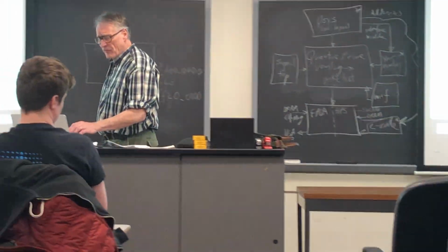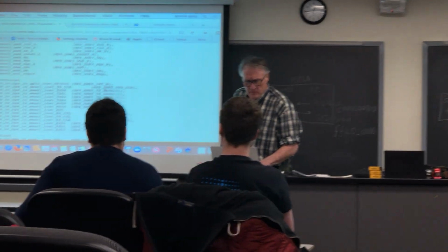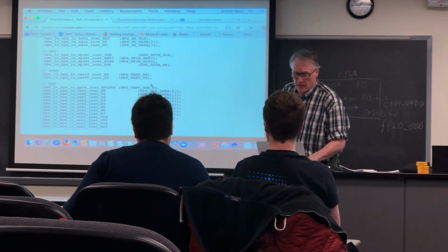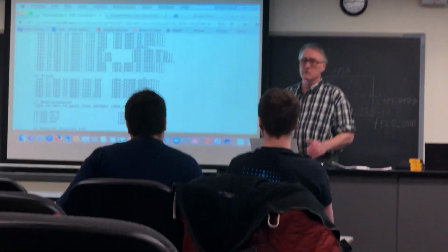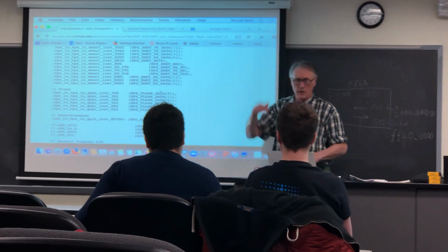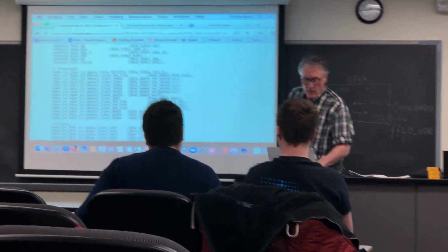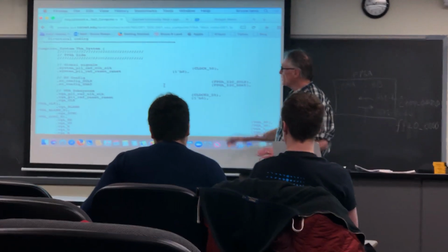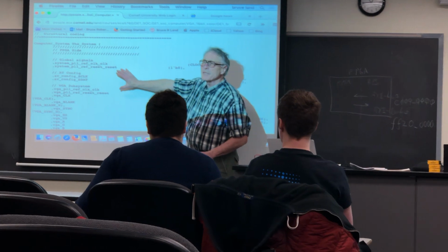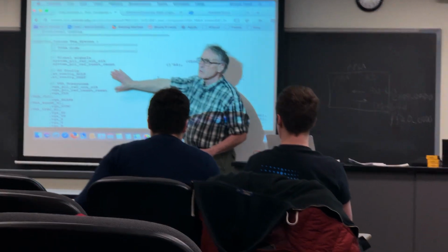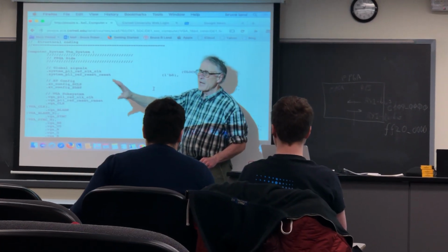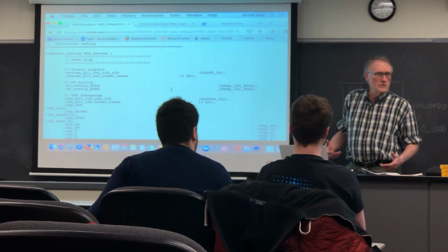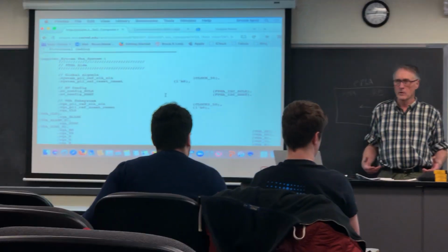This is a fairly big file. This version has been formatted into sections for your viewing pleasure. The default version that comes out of Qsys has no subsections. It's just one long blast of I/O linkage. So again, what I usually do, and what most people do, would be to change as little of this code as you possibly can when you add a new module. Add some signals, subtract some signals, but don't start from scratch. Just too many things to type.